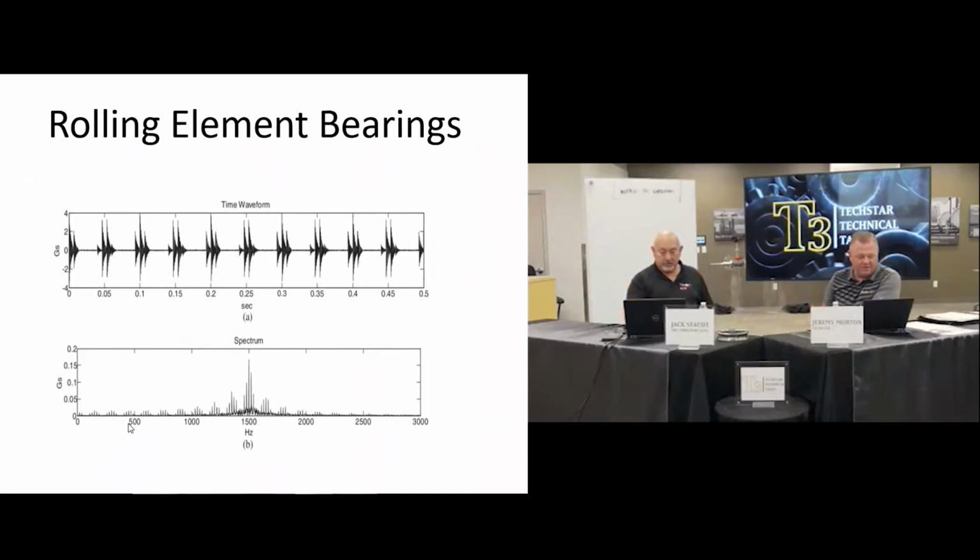And now here, in this spectrum, you're actually looking at a full spectrum. In your frequency domain, you have what we call side bands from your fundamental peaks and your harmonics of that. And that tells us a lot too. How far into the damage are we? We have stage 1, stage 2, stage 3, or stage 4 failure of a bearing.